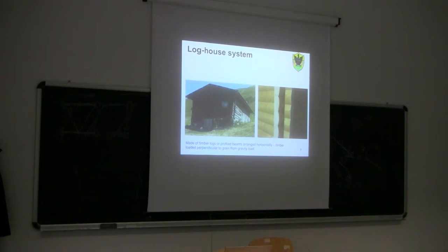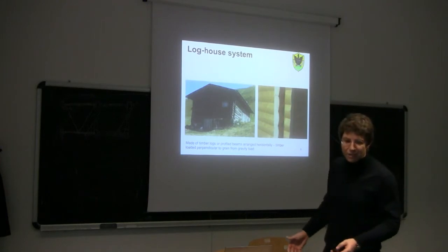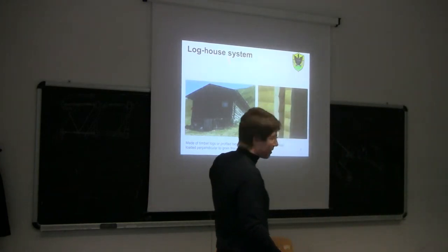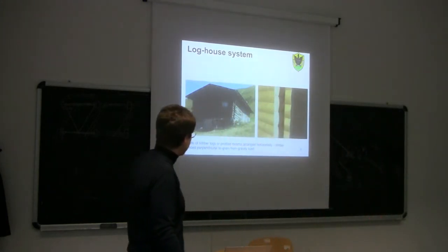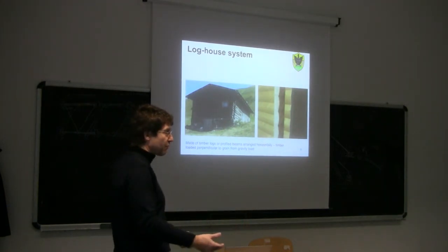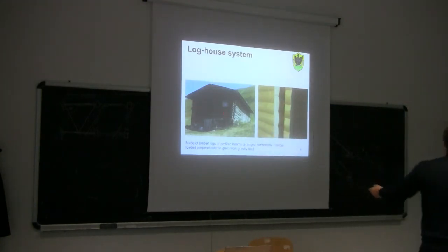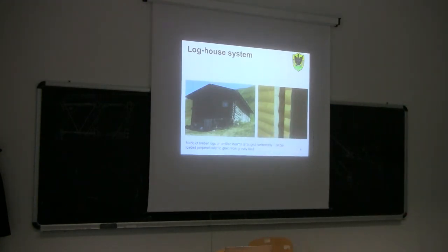But of course, since timber is stressed perpendicular to the grain, we can't think of building 10-story buildings in this way. Because it's clear that after 2 stories, the stresses will become comparable with the strength of wood perpendicular to the grain, and then we may suffer lots of plastic deformation. So with this system, we are talking about 1, 2, maximum 3 stories, no more.